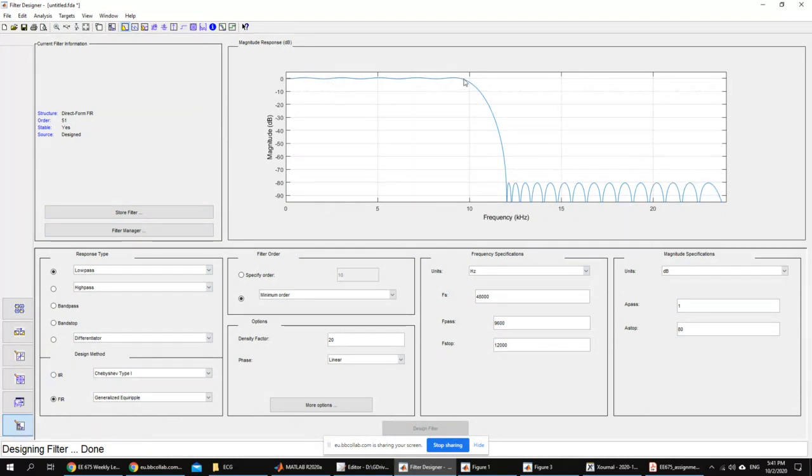Here, this is the part of the pass band. This is the part of the stop band. You see so many variations. In the frequency domain, this is not the case. It's either there or not there, meaning that it's multiplied by exactly 1 or exactly 0. So the pass band would look like a constant, and the stop band would be 0. That's it. Here we don't really care about the transition region. We just talk about pass or not pass. We don't have F pass and F stop in the frequency domain.